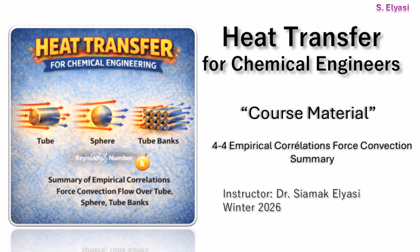And finally, what about pipes that aren't circular? Well, this is where engineers use a really clever tool called the hydraulic diameter. We basically calculate an equivalent diameter for something like a rectangular duct. This is a real game changer, because it lets us use all those standard, well-tested tube flow equations for almost any shape you can imagine.